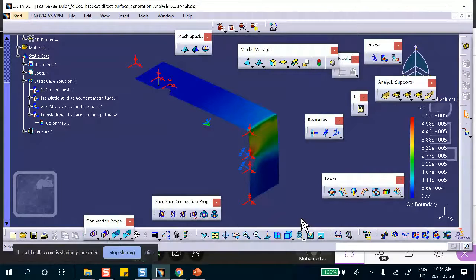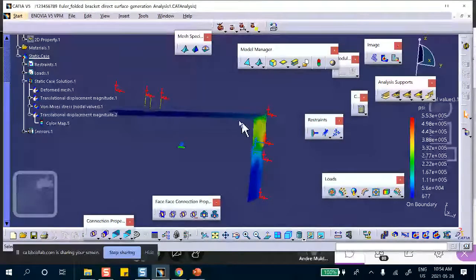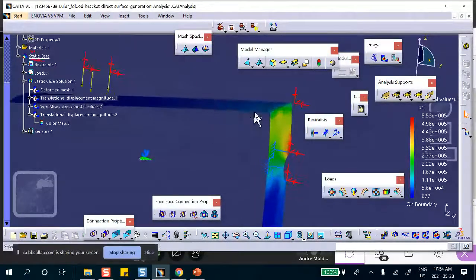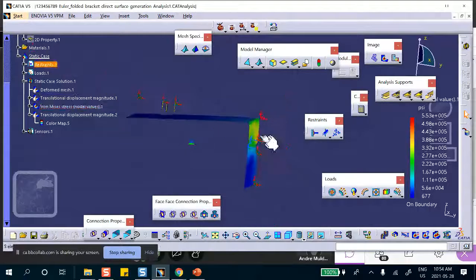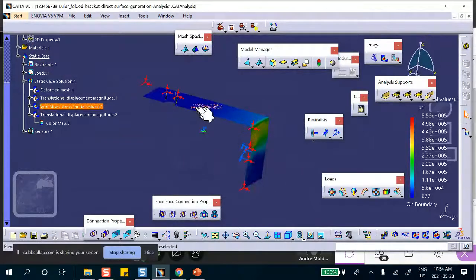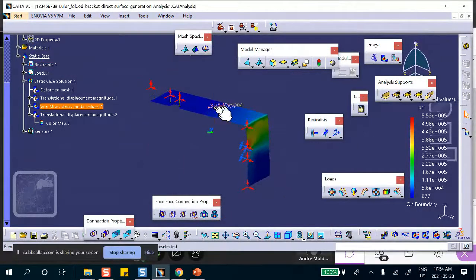What would you say? Use your common sense. Don't worry about engineering. You could put a bracket on the inside of the flange. Very good. For example, you're going to say, okay, I'm going to put stiffeners here. Or you're going to say, oh, I'm going to make this thing thicker, right? Agree?